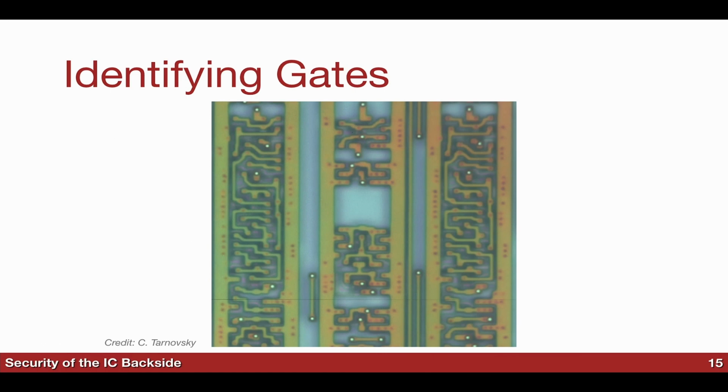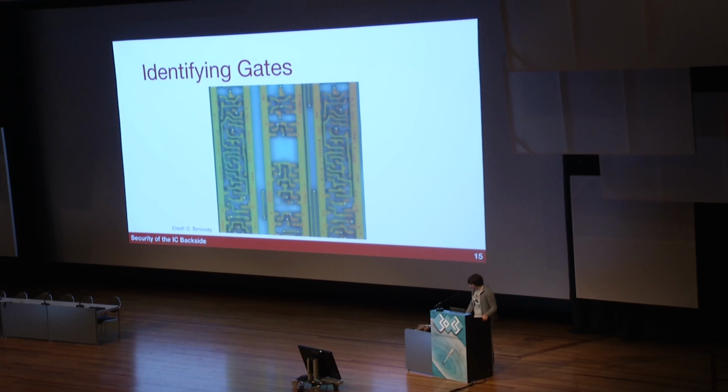Another thing which people underestimate, when they think about how you look at chips, is how much experience is behind it. And the reality is, a lot of people just haven't seen these kinds of images. So what you do, and the human eye is very good for this, is you look at a chip, and all of a sudden you say, hey, those look alike, and over here, those look alike on the sides. So in the middle you have inverters, and on the right and left you have flip-flops.